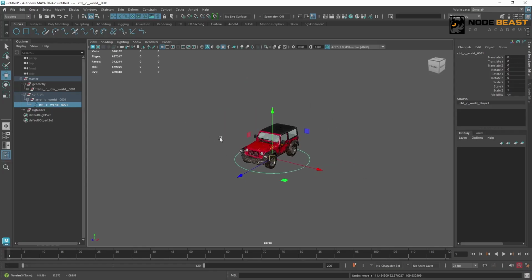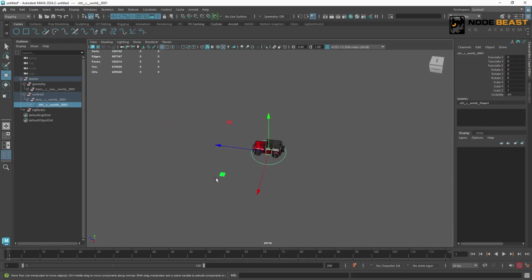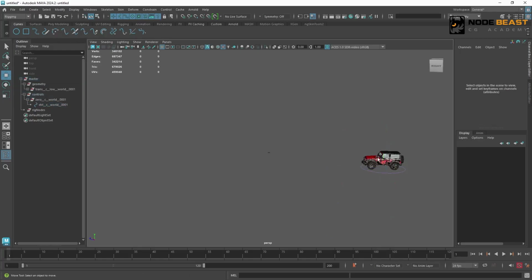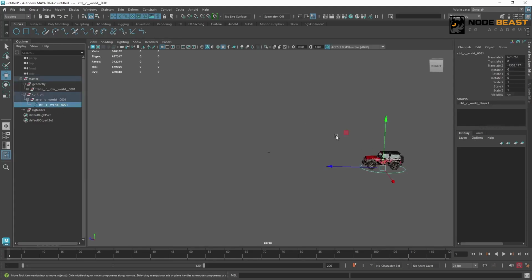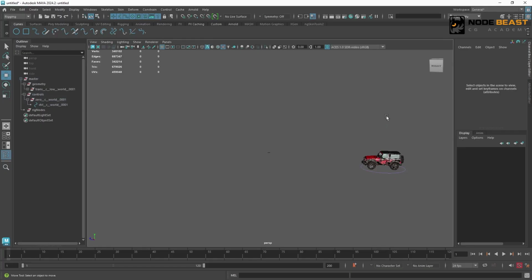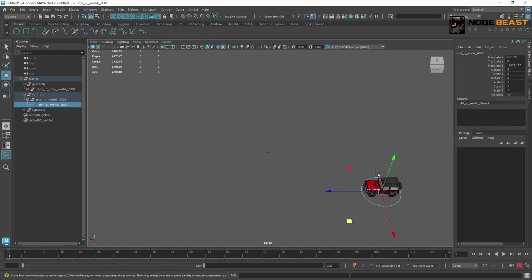Now we can explain in detail what the world controller's main job is. By default, models are at the world origin, but in an animation scene, it's very likely it won't start from the world origin. It might start from, say, this position. At this point, we need to move the world controller to this position. This car will have other controllers later. When we use other controllers to animate, it will start from this position, because they will all be children of the world controller. So when we zero out these controllers, their position will be at this current position, treating this position as the initial position.